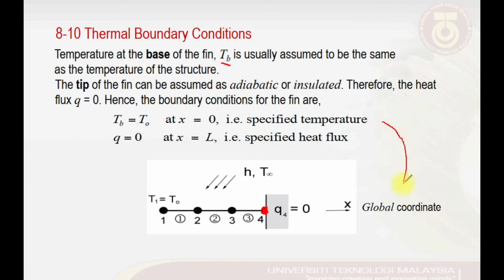As I mentioned just now, if we put the thermometer on the surface of our structure, we get the reading of the temperature on that surface. Similarly, if we place the fin on that particular point where we measure the temperature, the temperature at the base of our fin will be the same as the temperature on that surface as we measured just now using the thermometer or any kind of thermocouple.